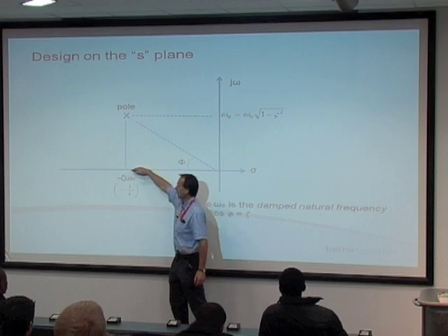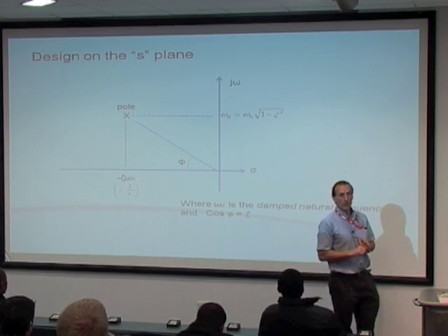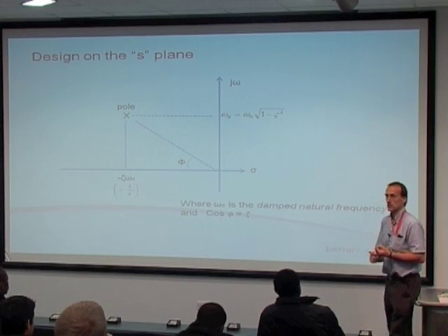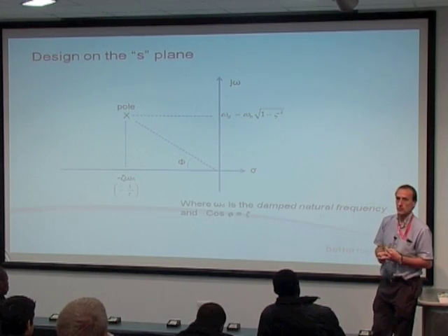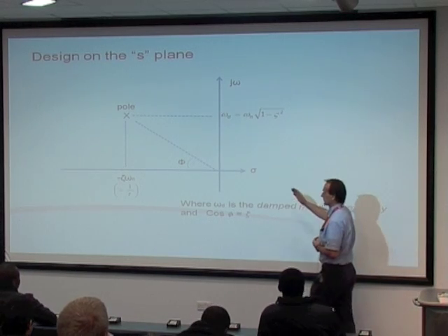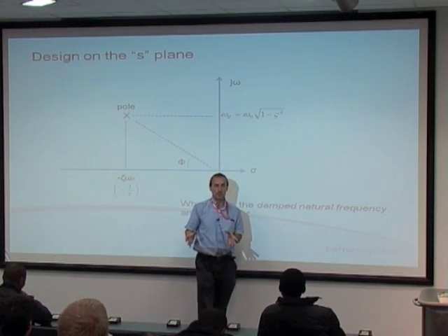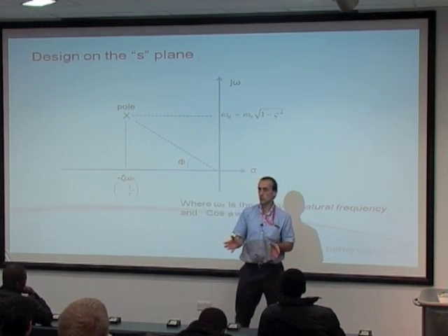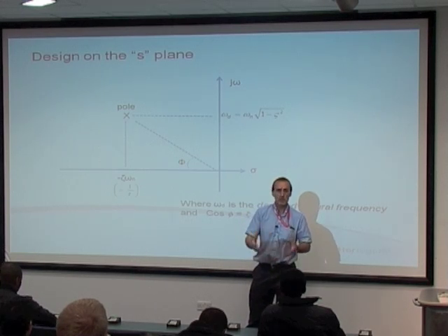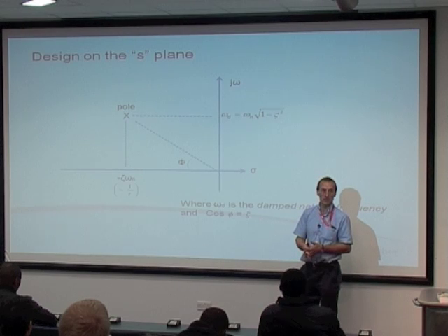So we end up on this real axis. Zeta equals 1, if you recall, represents critical damping, which has got no oscillation. Okay, and our pole has been pulled down onto this axis, which is really the same place as a first order pole would be, and the behavior is really linked to first order sort of behavior.